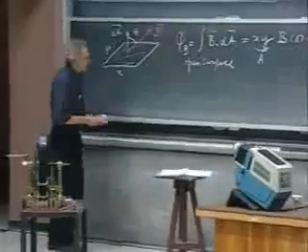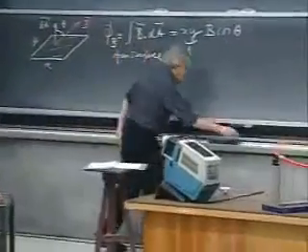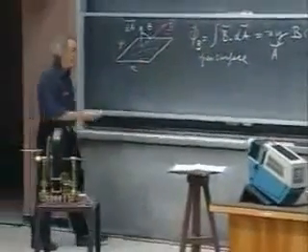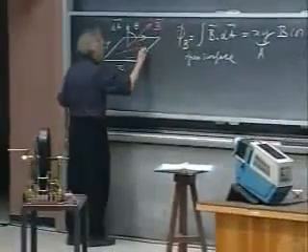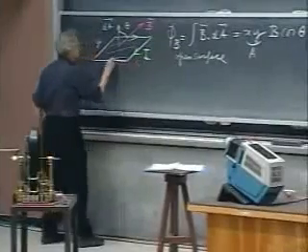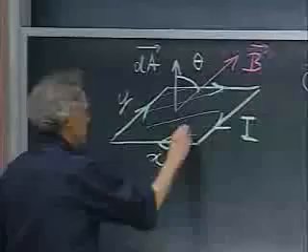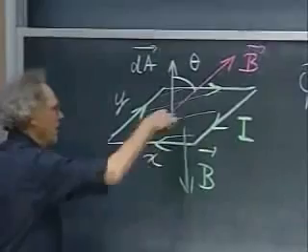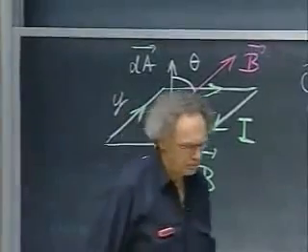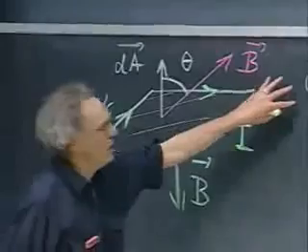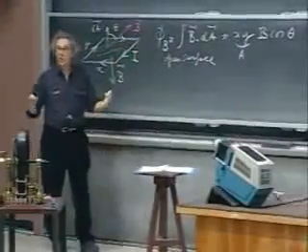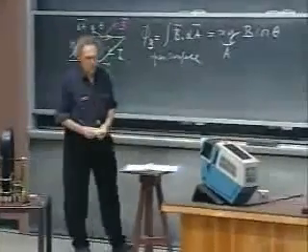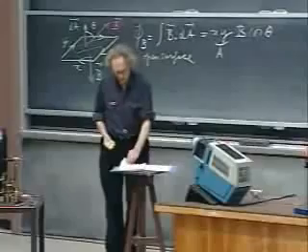So if the flux, which is now positive, is getting larger positive, then the current that's going to run will be in this direction. That's Lenz for you. So this current will create a magnetic field in this direction. And if the magnetic flux, which is now positive, the way I've defined it, were decreasing, then the current would go the other way around.